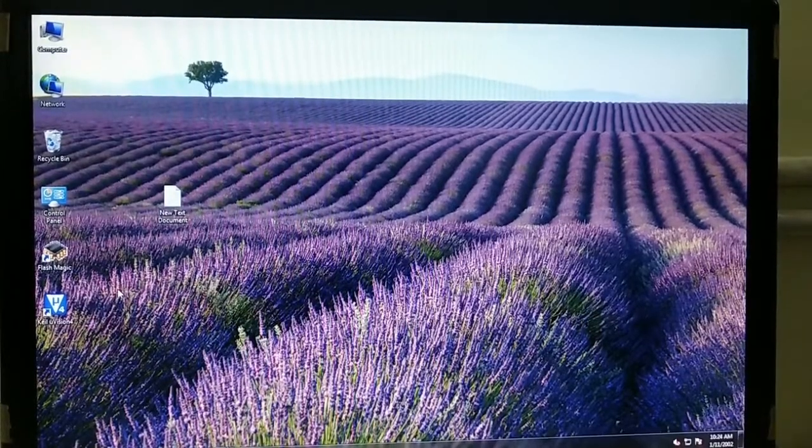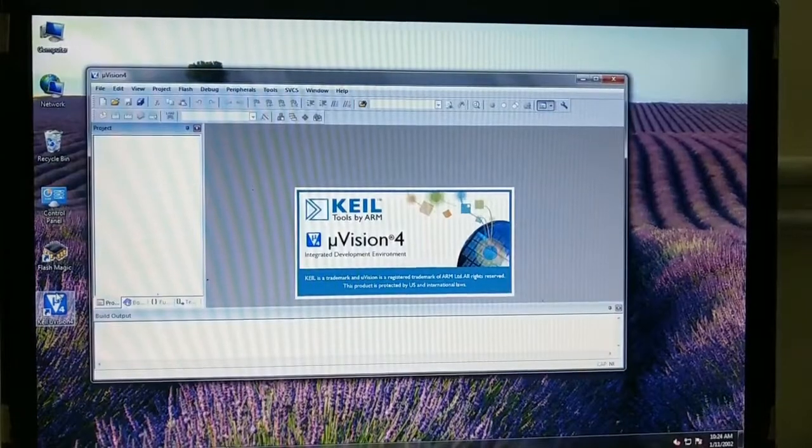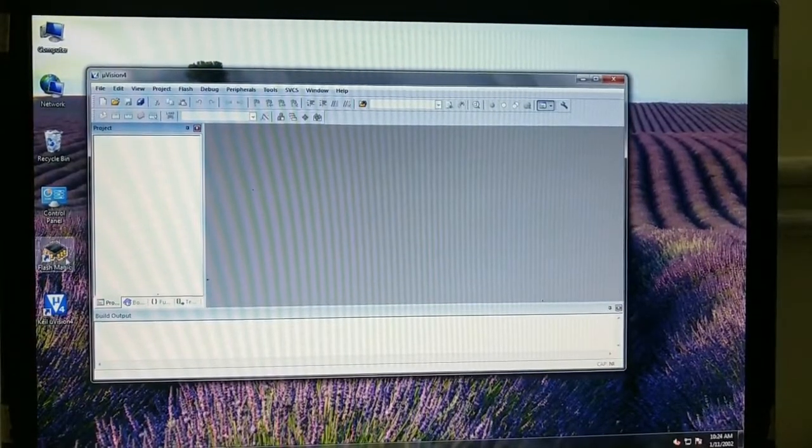The software part is what I am going to show, such that the program gets executed and you are going to see the stepper motor rotating in the clockwise as well as anti-clockwise direction. Right, I'll show you the steps for execution. Firstly you need to open this Keil software by double clicking on the icon, and then you need to start with a new project.